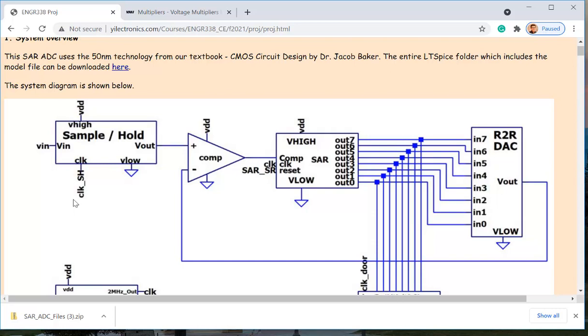So anyway, whenever you are trying to use a new PDK, you have to install it to Cadence in order to use it. Electric VLSI does not allow you to install any Cadence technology, like TSMC 180, the most modern technologies. You can only use C5 or the 300 nanometer scale. We are using 300 nanometer as 1. And the minimum size will be 2, which is 2 times 300 nanometers, which is 600 nanometers.